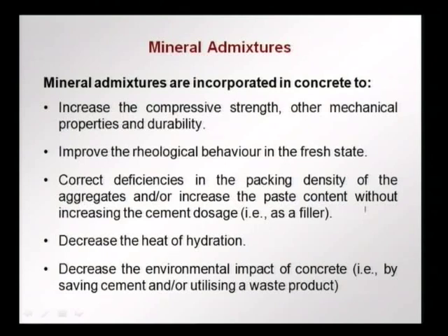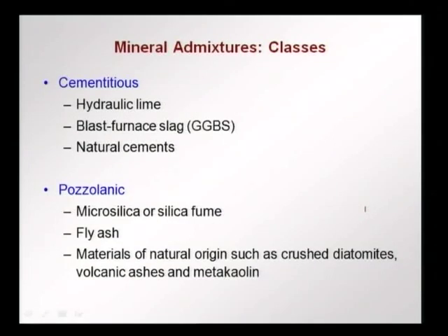So there are a lot of benefits in using mineral admixtures, and in India today most of the concrete will have some kind of mineral admixture, either coming in through the cement itself as a blended cement or being added to the concrete at the mixing plant. What are the different types of mineral admixtures that we can use? We classify them as cementitious, pozzolanic and inert.